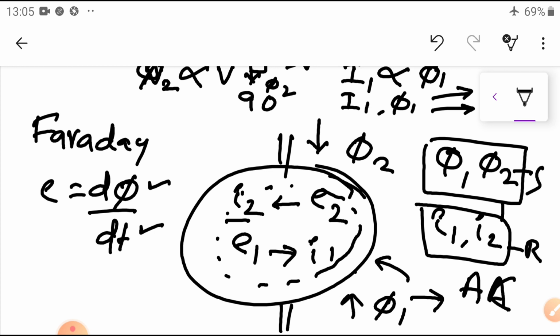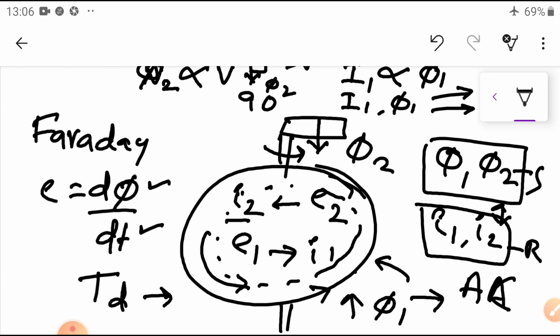Due to this, what will happen? Due to the interaction of the magnetic fields, a deflecting torque is produced. Due to this deflecting torque, the aluminum disc will try to rotate in the air gap between the shunt magnet and series magnet. So there is a mechanism provided. It will slowly rotate. Once it rotates, the spindle also rotates and there is a worm provided here. It will count the number of revolutions of the disc.